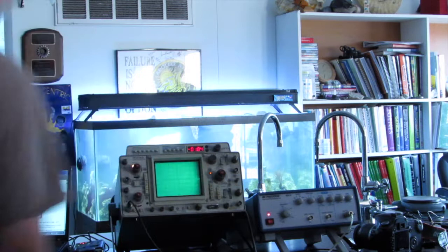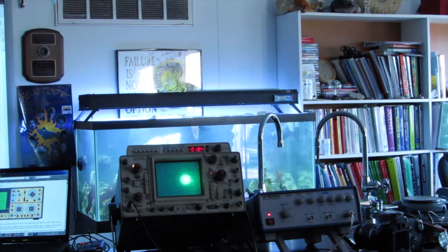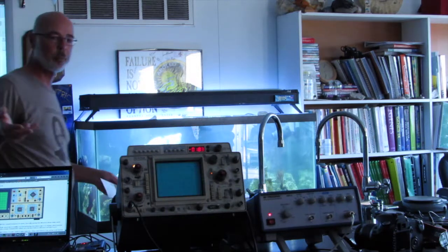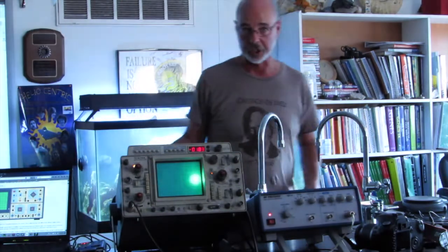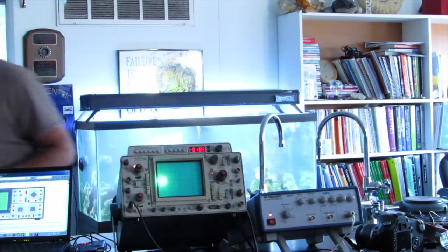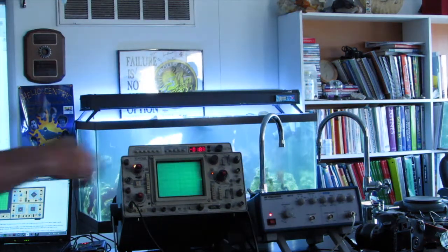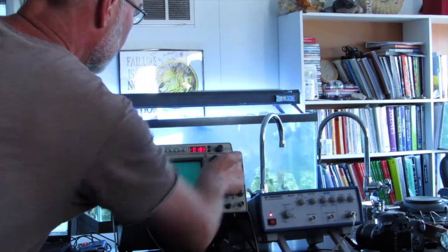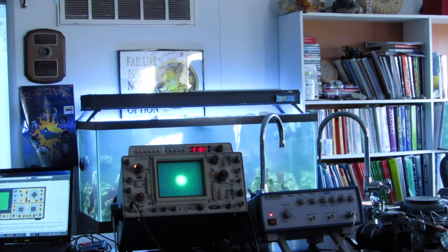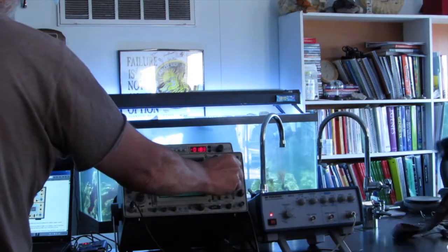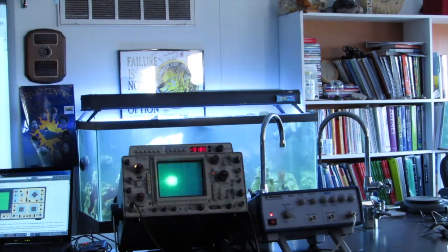So this is just the horizontal sweep doing its thing, okay? That setting right now is set for, I think, about 1 second per division. Okay, there's 10 divisions on the screen, so it takes about 10 seconds to sweep across the screen. I think I'll have it set a little faster than that. We'll set that. That's one sweep per 1 second per division. Okay. All right. So the horizontal section, and this is on every single scope.